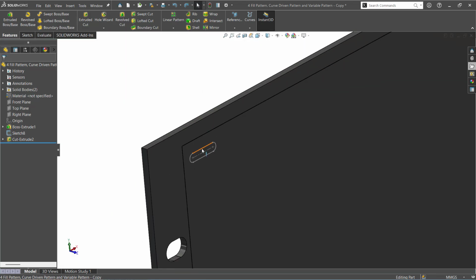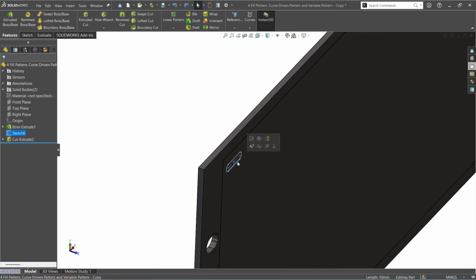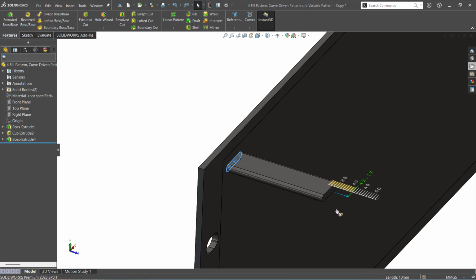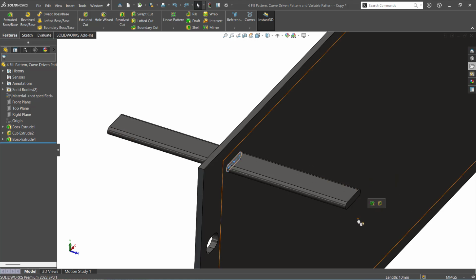Now I want to remove the material. I can drag both the sides, but I showed you the shortcut also. You can do it like this. Select this and drag it. If I drag it this side, it is extruding, but I should also remove the material that side. Hold the shift and drag. So now both sides' material got added. Now if you release it, it will show you the quick access. So instead of extrude, you can have the cut.